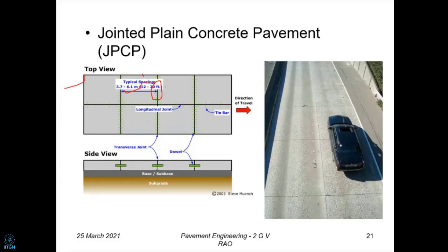So depending upon how we calculate stresses now, we have a frequency of the dowel bars now, spacing and all. So there's a system for that. If you are interested, we can deal with that also. And then these are actually also joints between one lane and the other lane actually. They are the longitudinal joints now. So sometimes the slabs can warp also.